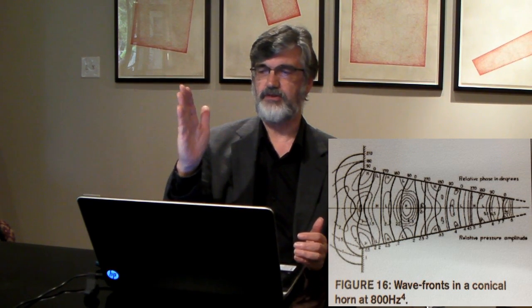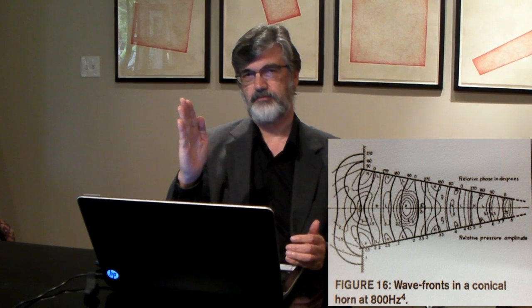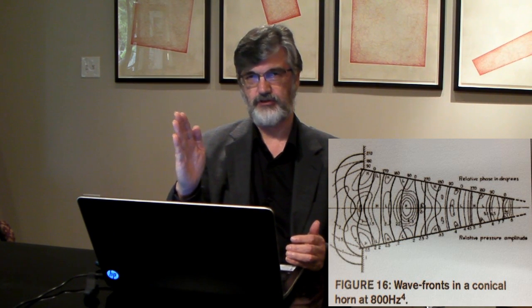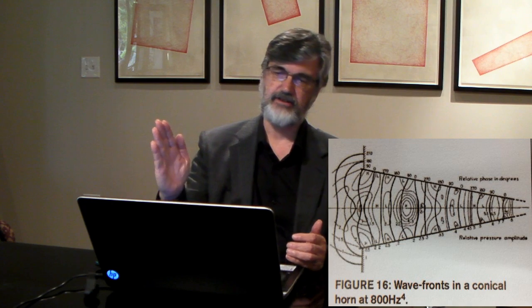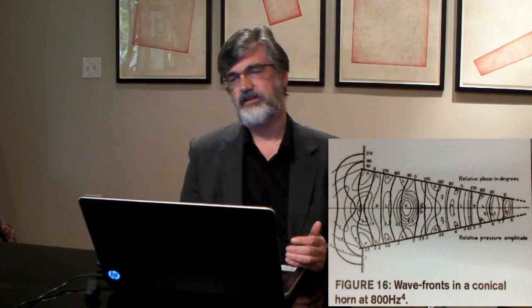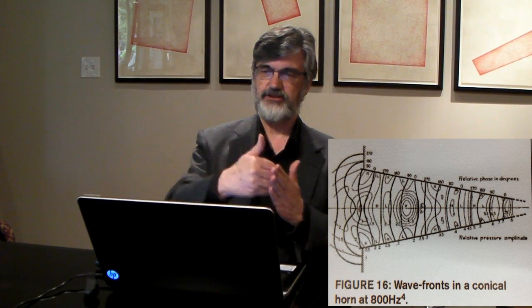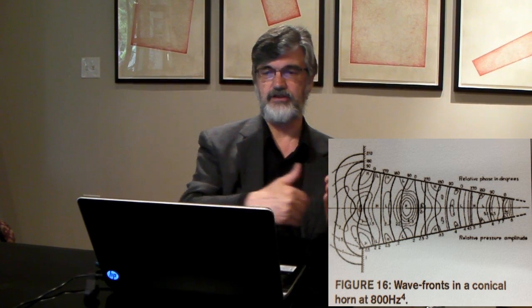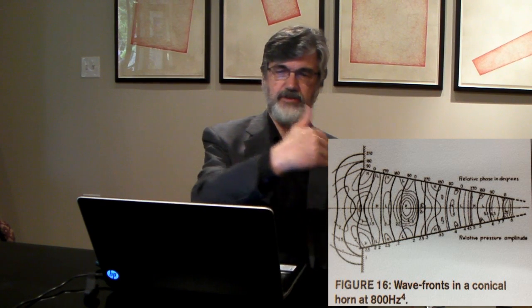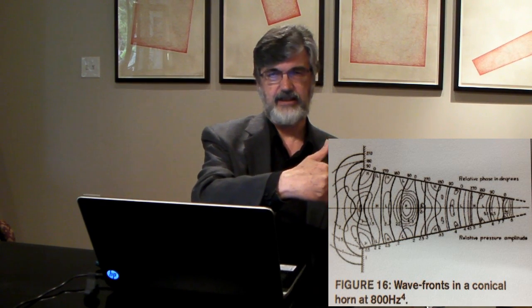If you could come up with a perfect planar sound source, no phase distortion at all at the mouth of the horn, and then progress it through the horn, you'll see that it changes phase, it has phase collisions all through the horn itself, and by the time you get to the mouth, you again have chaos. So both technologies have inherent problems making distorted sound.